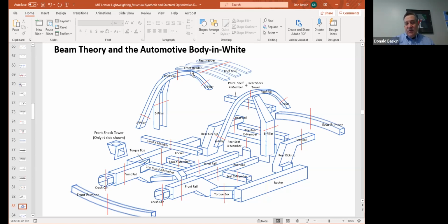And this is a place where almost always you see a lot of martensitic steel. For example, a lot of modern cars have martensitic B pillars, and the same with the roof rail. This is a scenario where it's really preferable to not make these parts out of aluminum. Even if the rest of the car is aluminum, a lot of times these parts are better off made in steel, because you don't have the packaging room. There are two reasons you want to use martensitic steel.